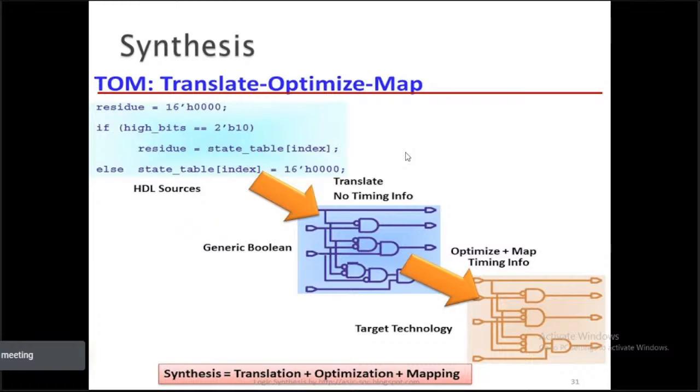So it depends on the customer requirement. If they are saying 3 nanometer, 5 nanometer, or whatever their requirement, on the basis of that we first create the standard cell library. Standard cell library means the AND gate, NOR gate, all types of latches, flops, which we optimize. We do the full custom design for the standard cells, then we make their library and we use those libraries in our main design for making an SoC.